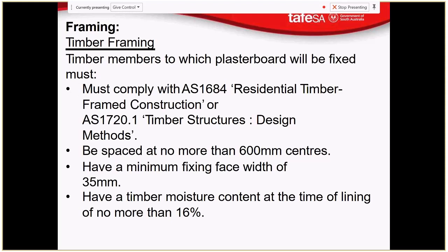or seasoned outside. Seasoning outside, or seasoned in controlled conditions, takes a very long time. It's typically done for hardwoods, because hardwoods can split as they lose moisture, more than our softwoods like pine.